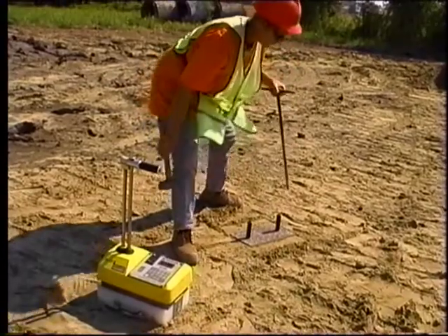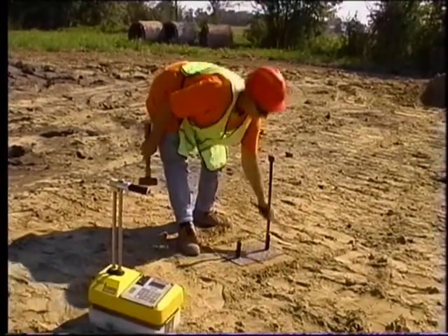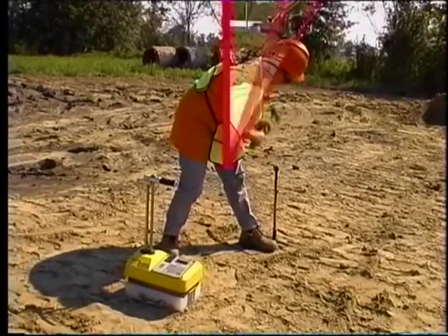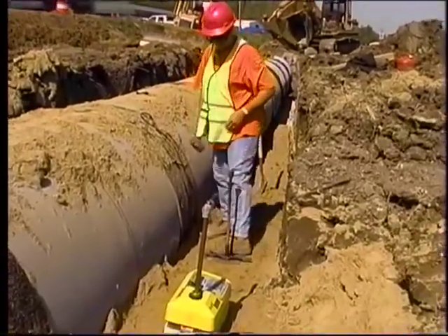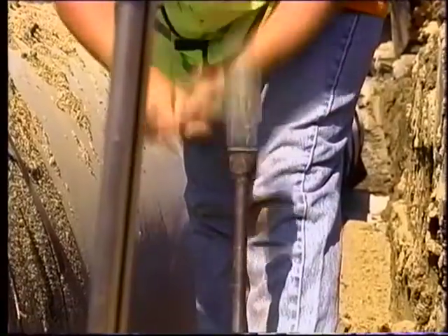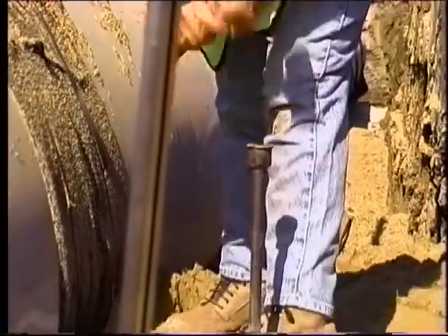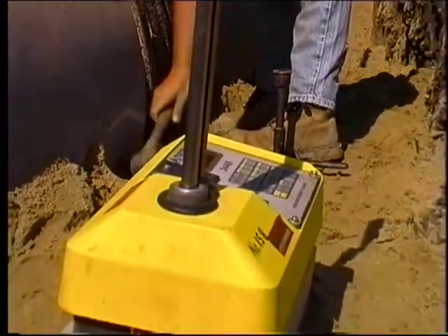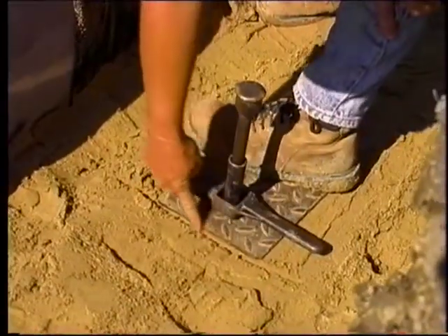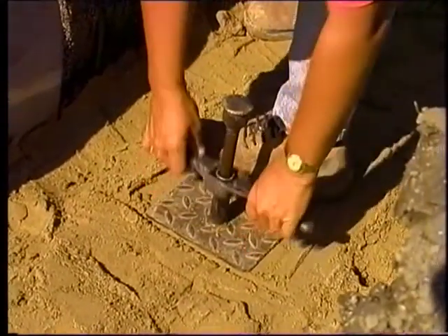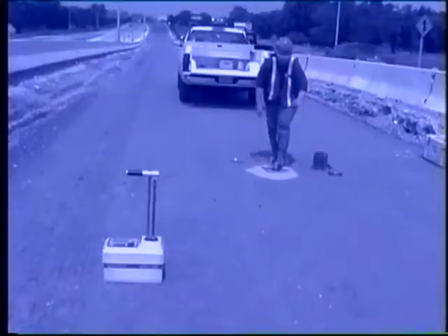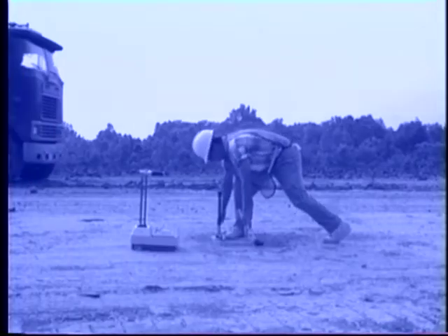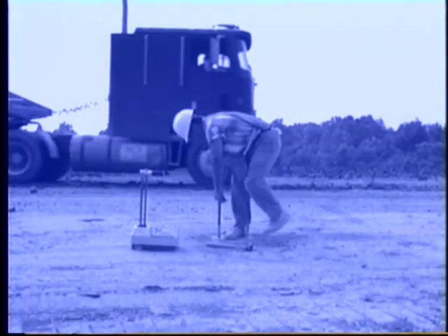Using the scraper plate drill rod guide, the drill rod, and the hammer, place the scraper plate at the location you have just prepared. Put the drill rod through the extraction tool and then through one of the guides on the plate. Put 1 foot on the plate to hold it firmly and hammer the drill rod at least 50 millimeters or 2 inches deeper than the test depth to be used. Before removing the drill rod from the scraper plate, mark the test area to make it easier to place the device over the site. Remove the drill rod by pulling straight up in order to keep the access hole intact. Use the extraction tool if necessary.